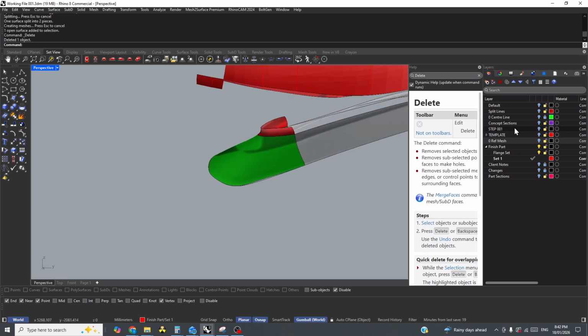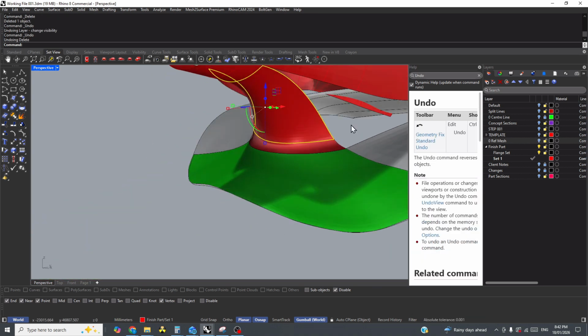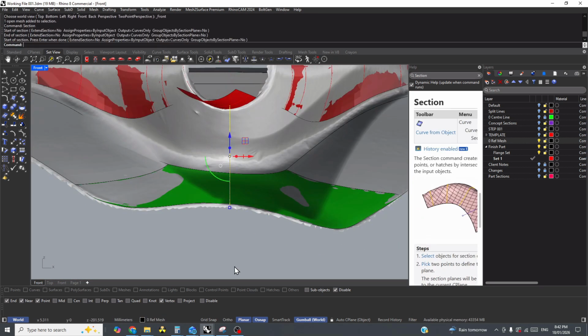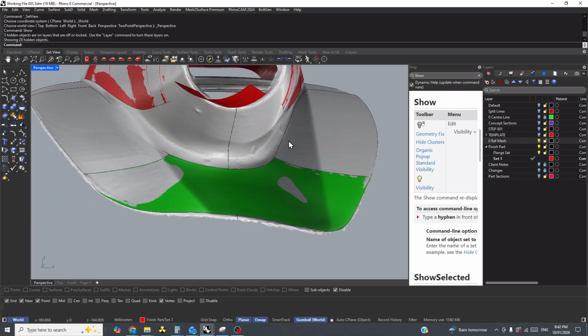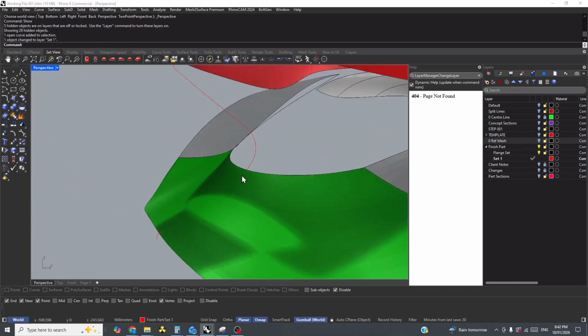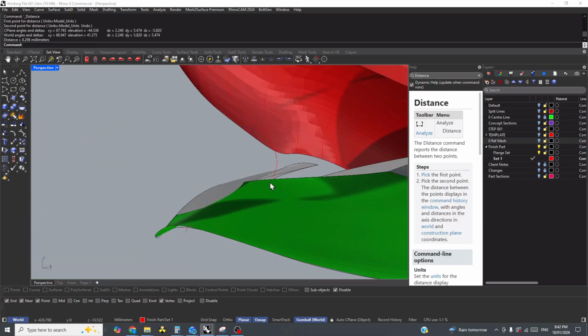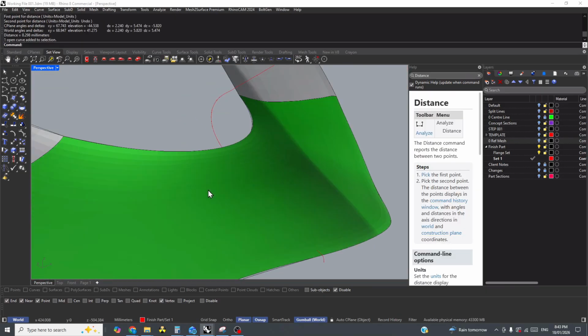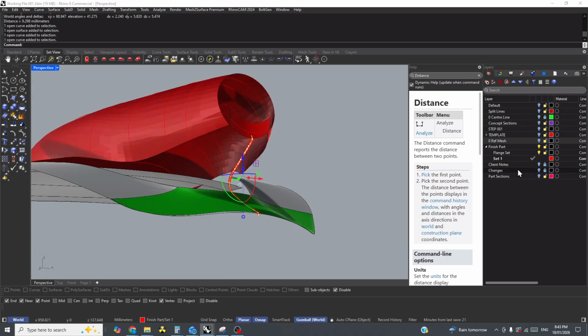So as I said, at the start of a job, even do a simple loft, change it to rebuild with 30 points, hit OK. That is if your curves are a bit point dense like mine often are, and that will save you some time and complexity.